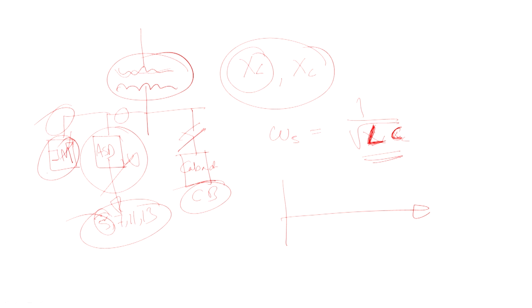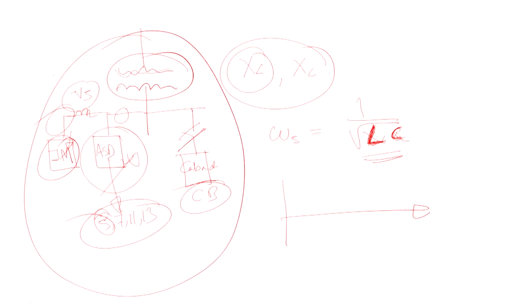Because of the source inductance of this wire, this 5th harmonic voltage will also be generated, and that will go into the machine and ultimately produce a ripple torque, a torque negative to the fundamental movement, and thus cogging will take place.